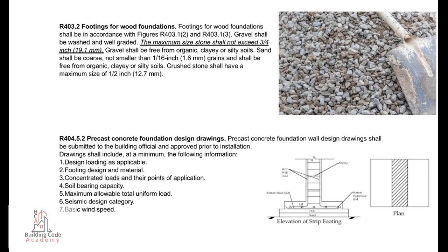R403.2 Footings for wood foundations. Footings for wood foundations shall be in accordance with figures R403.1.2 and R403.1.3. Gravel shall be washed and well graded. The maximum size stone shall not exceed 3/4 inch, 19.1 millimeters.